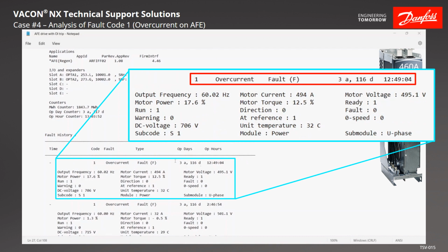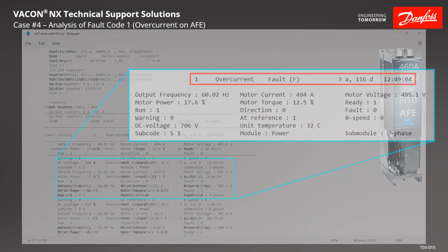4 seconds. Now by default, the drive will put in a power on counter here. If you do set your drive with the real-time clock, it will put a real time in here. So if you are starting to troubleshoot something, it may not be a bad idea to go into the drive and set a real-time clock to the drives, and then it'll give you the exact time that the drive trips out on, as long as the drive doesn't lose that real-time clock.